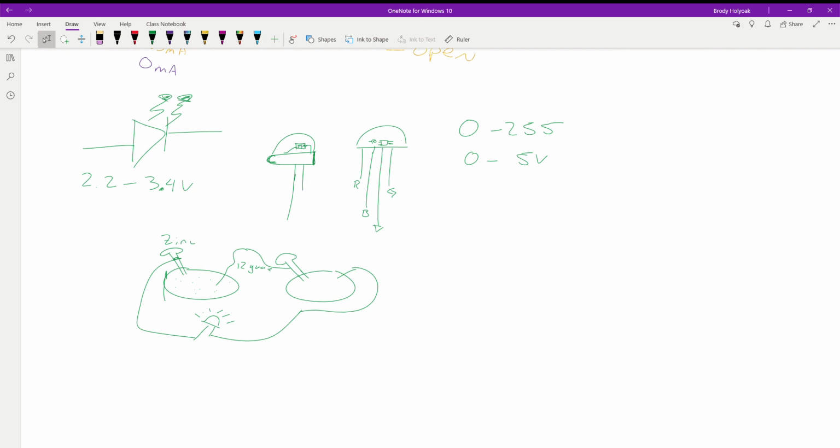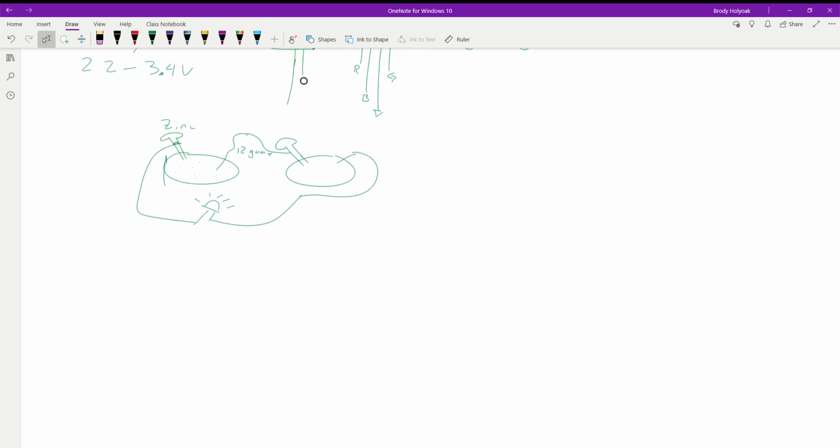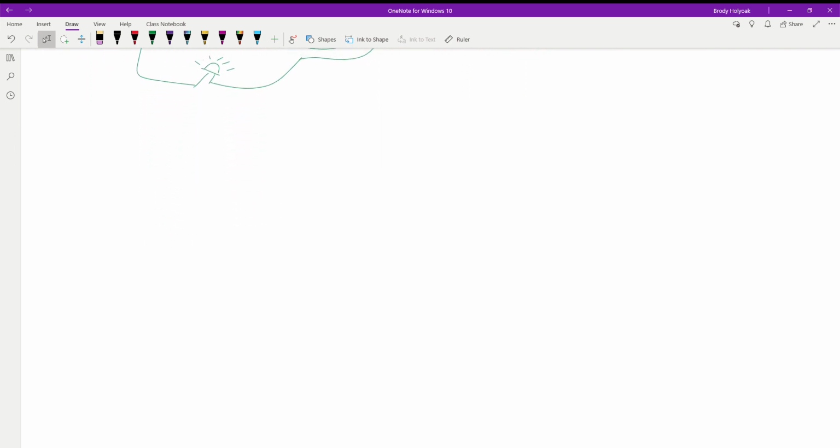That's an LED. They're very simple, but again, it's how you wire them up. The flat side is the negative. It's also the shortest leg. If they've been cut, obviously you don't have that reference anymore, but you still have the flat on the LED. Questions about the LED? You guys are going to use these things a ton. They're also one of the biggest drains on batteries.